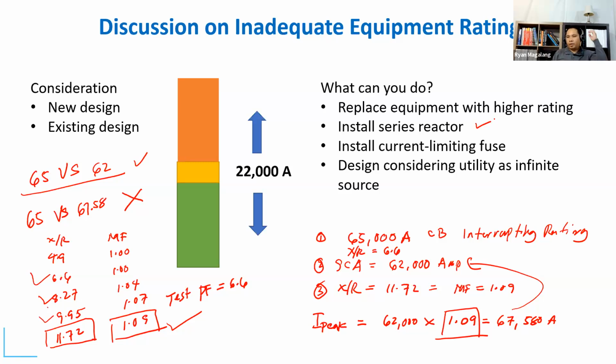Because it doesn't happen overnight. Like I said, every 5 years or so, we are mandated to do a study to analyze what has happened, whether the fault current is increased. But anyway, what I'm saying is, now you are facing this situation where the fault level in your area has increased, and now your devices, your switchgears, your breakers are no longer suitably rated to withstand that magnitude.